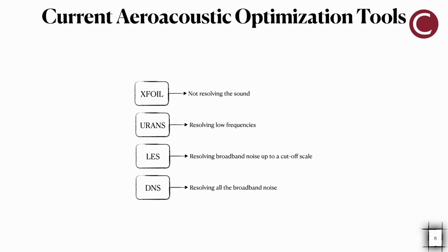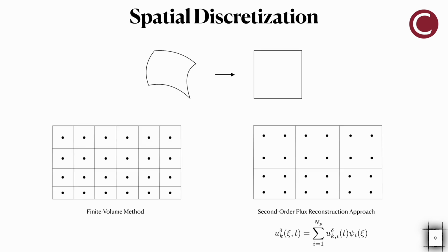So now let's talk about the other component of the CFD simulations, which is the spatial discretization. When we're dealing with fluid flows, we often encounter irregularly shaped elements, and we map each of these irregular elements into a reference element. This technique allows us to work with familiar shapes, which simplifies the mathematical equations we need to solve.